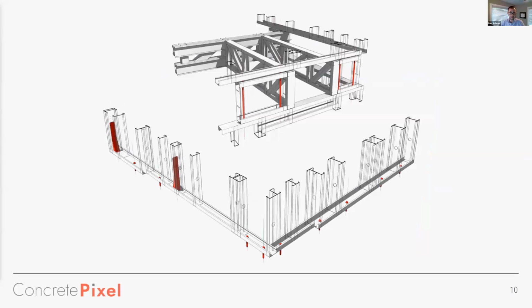So another benefit is design and coordination of anchor bolts. They're usually not considered to a great extent prior to construction in the field. Prefab of wall panels means there's very little room for error during installation, and a single misplaced bolt can cause some pretty significant delays, which negates the primary benefit of prefab, which is saving time. So to avoid issues, anchor bolt coordination can streamline installation.